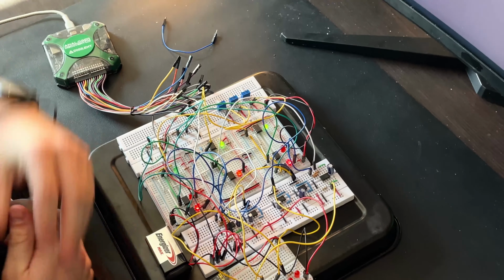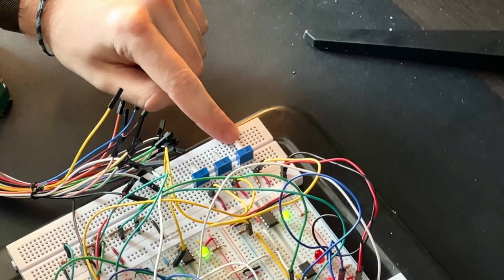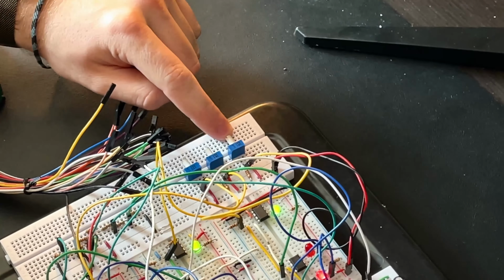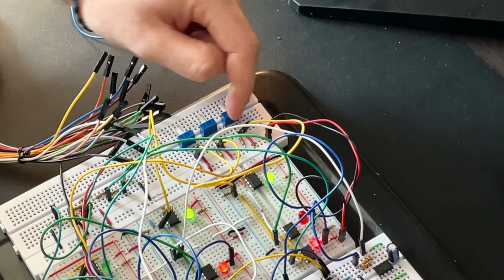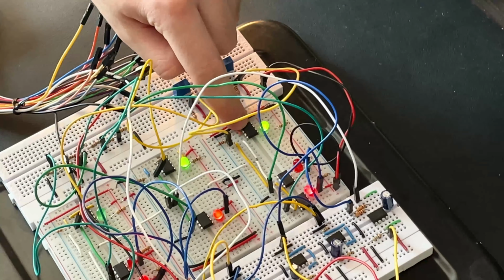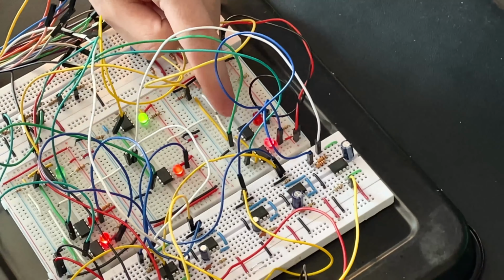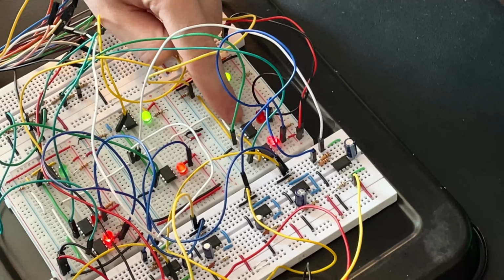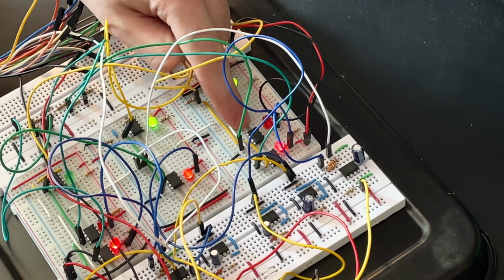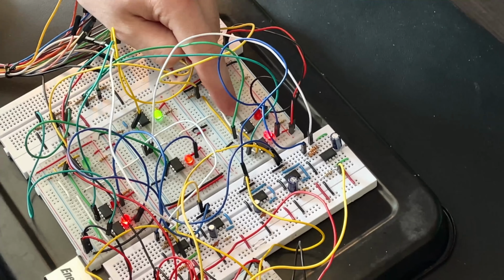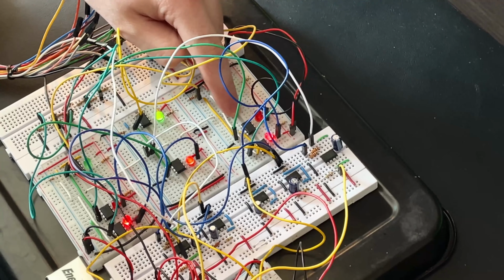Cool. We're going to take a look at the oxygen sensor, still simulated by a potentiometer for the sake of power and simplicity. Take the output of this pot and run it into this board here. This lets us know we're in activity. And then these comparators have been changed a little bit from MS1. One of them is now active low, and that has to deal with the fact that it's hooked up to a monostable multivibrator, and because that's falling edge trigger, we need a falling edge signal for it.